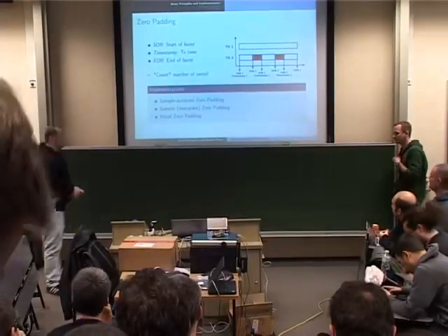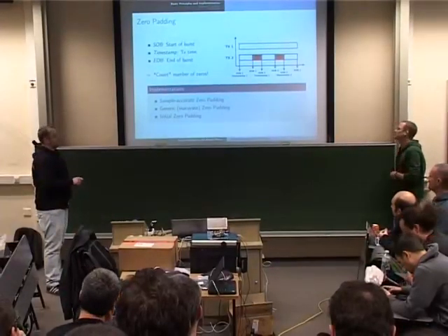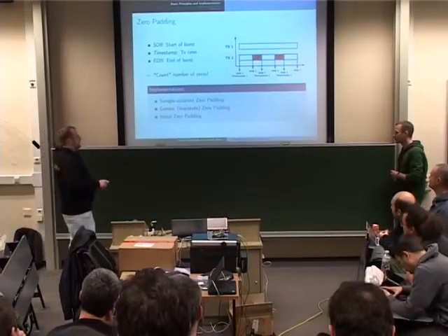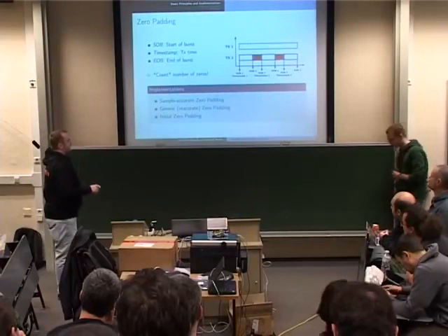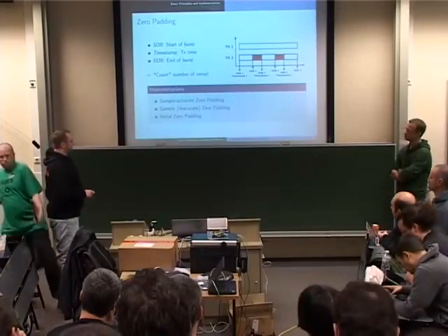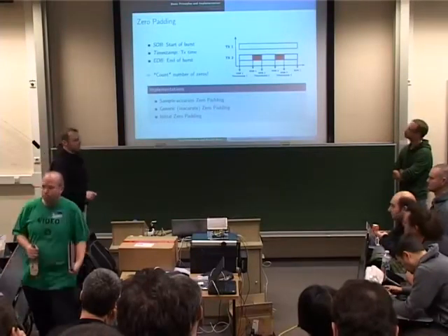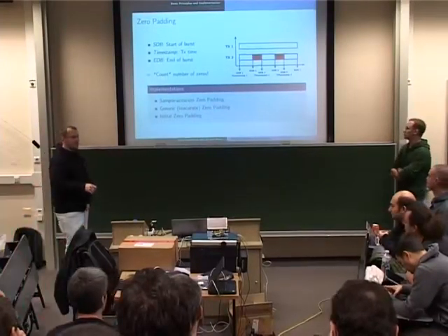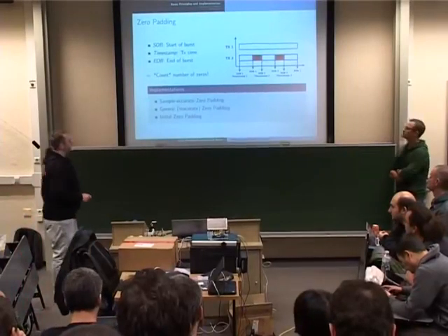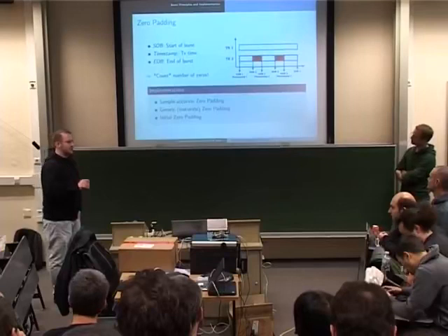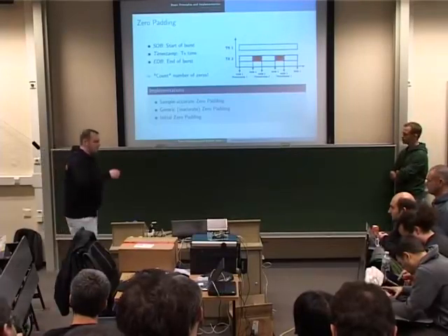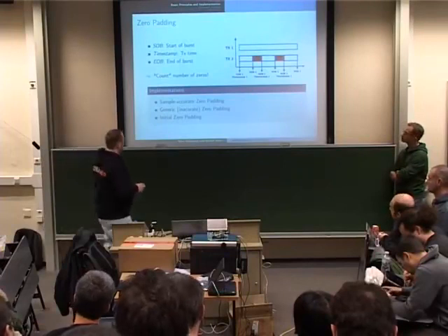So we implemented a method that starts producing noise or zeros or anything and distributes them to all the receivers, until it gets a timestamp. Then it calculates how much it had produced already and how much it has to produce in the future. And if it produced too much, it gives you a warning and error and says, stop, here's a simulation error. So then you have to run the simulation a bit slower.